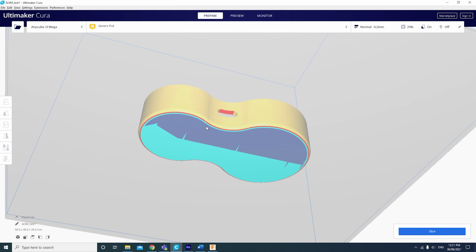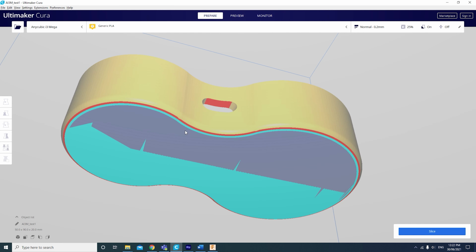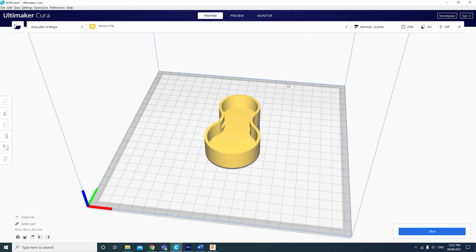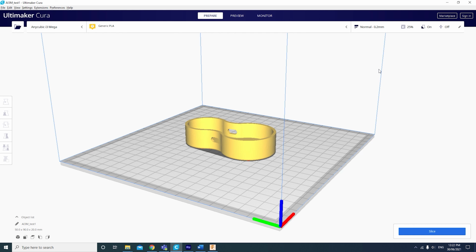As you can see, the edge of the 3D model actually has a slight radius. That means that there might be issues relating to the print actually peeling up at the edge as a result of it not being fully stuck down. While the Anycubic Ultra Base is quite effective at holding onto the print for PLA, it can still have issues related to warping if the bed isn't perfectly flat or if the first layer is put down a bit too quickly.